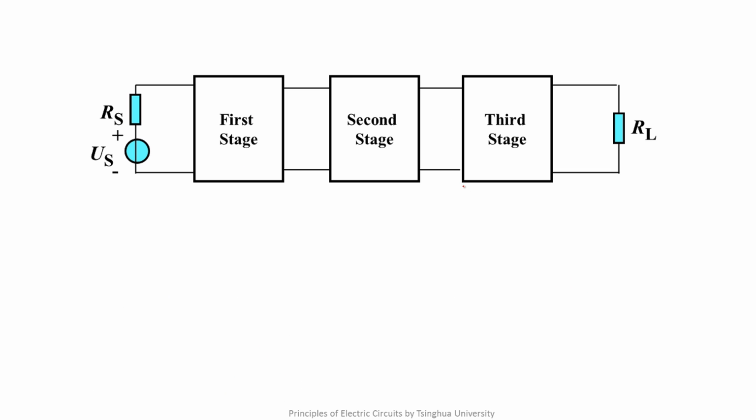The following discussion is about the application of the actual voltage signals. Firstly, we need an input stage, which can sample and transmit a weak voltage signal with no distortion to the next stage. Secondly, we need an amplification stage, which can amplify the weak signal. Thirdly, we need a drive stage, which can use the signal to drive the load. These three stages have different functions.